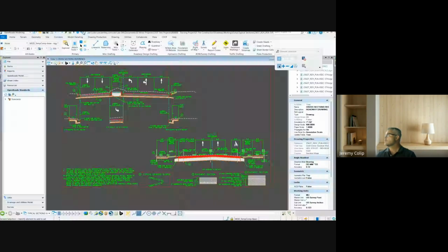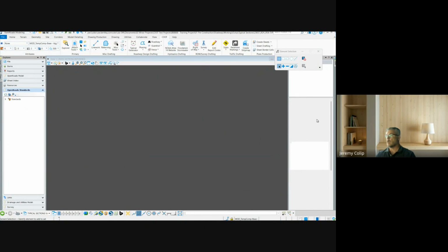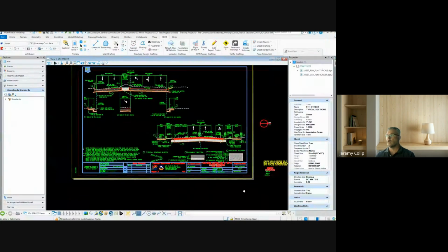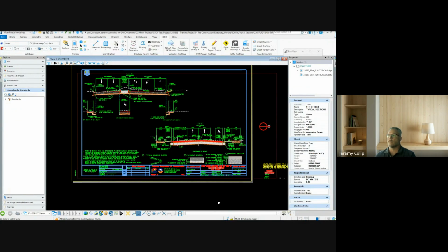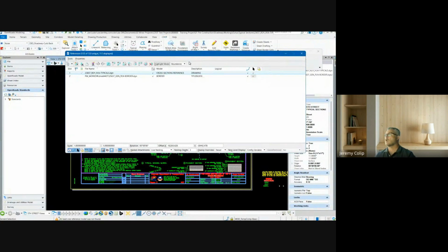So similarly, you will end up with the drawing model, and then your sheet model, like Schwab showed, and you can see here's the symbol moved over to the right. The same thing, the sheet's set up now, it's referencing that drawing model that we have in. Notice it's a nested depth of 3, because we've got to bring that information across into my sheet.